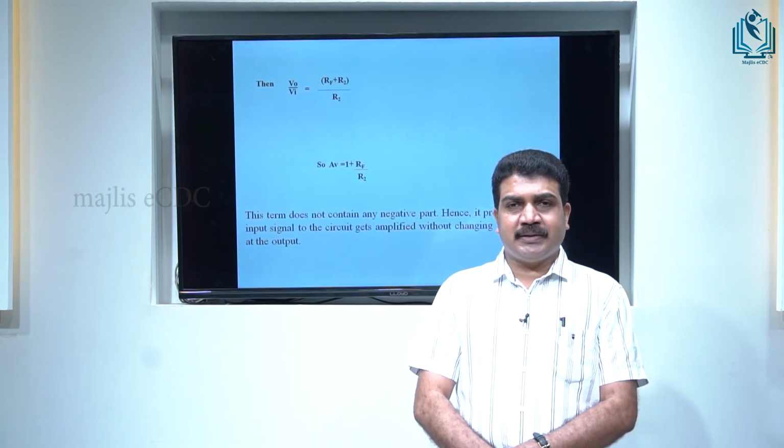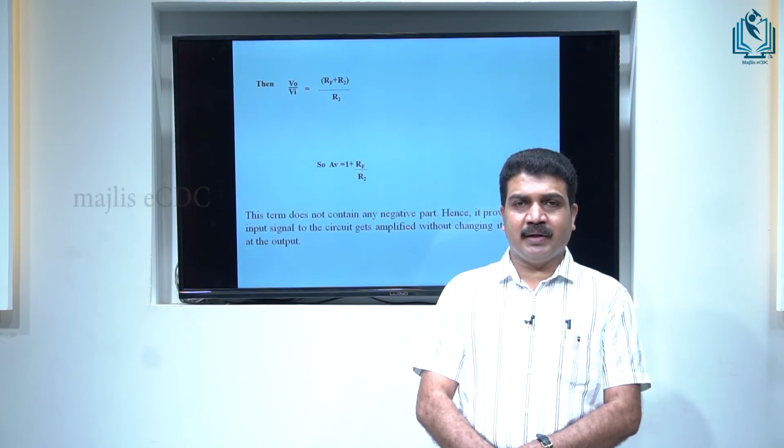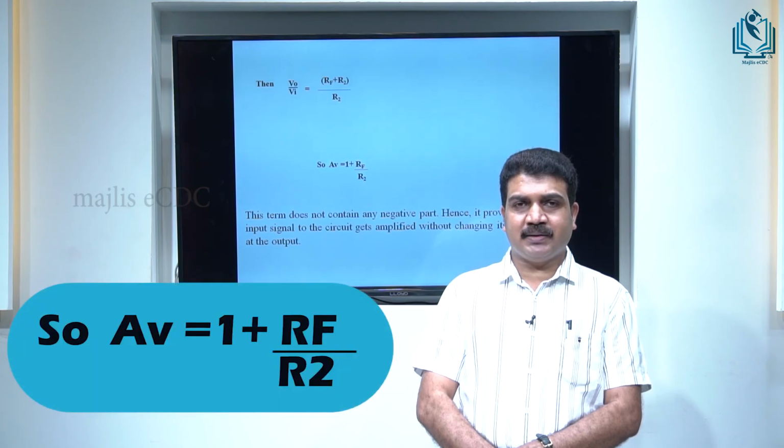From this expression we can see that there is no phase reversal, that is, there is no negative sign. The gain of the circuit is 1 plus Rf by R2.